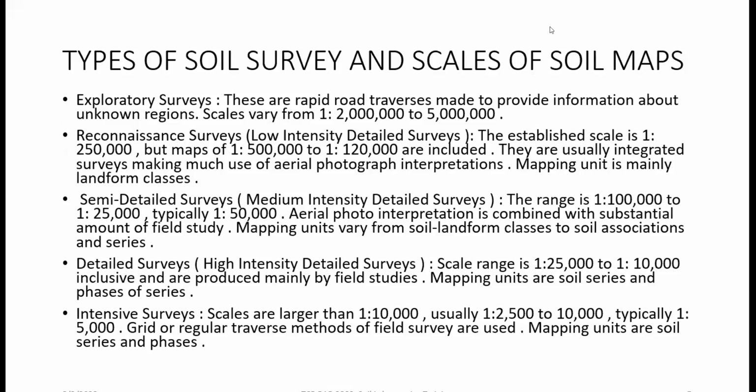Are they considered the same sample? Do we mix them or consider them different samples? If the soil is not homogeneous, it is different, so you have to take it as a single one and not mix them. When there are changes in color or changes in slope or other factors, you treat it as a different one, not mixing them together.